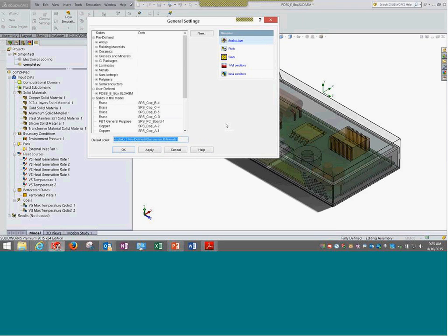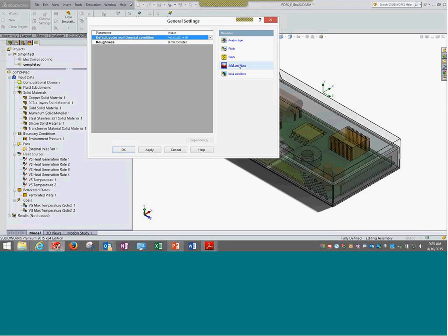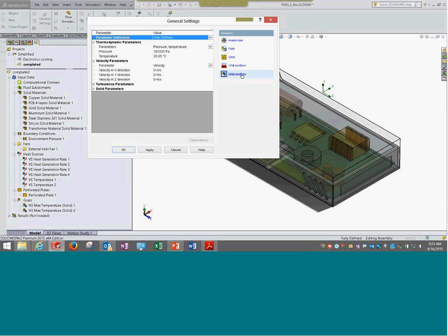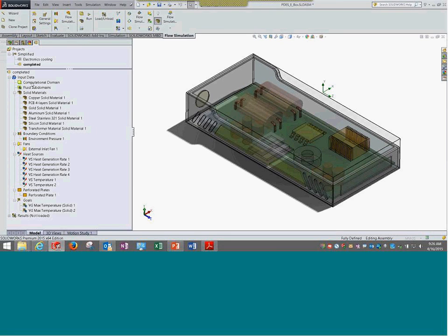The way we want to do it is, a material which is present in the maximum number of components, that material you can use over here, and for the rest of the components you can manually give the different materials over there. Nothing much. Adiabatic wall, no heat. We are not simulating the heat dissipating to the atmosphere through the walls. The temperature is not changed in any of these parameters. It is all the same. Okay, so this is how it goes on.